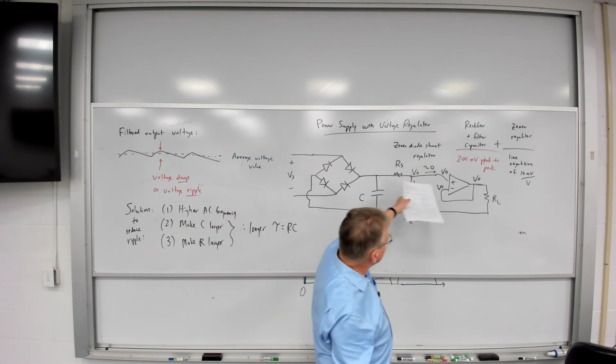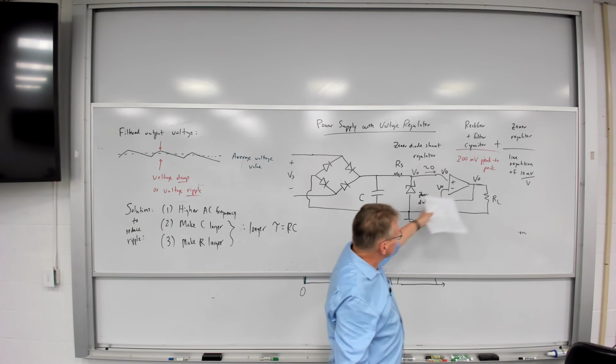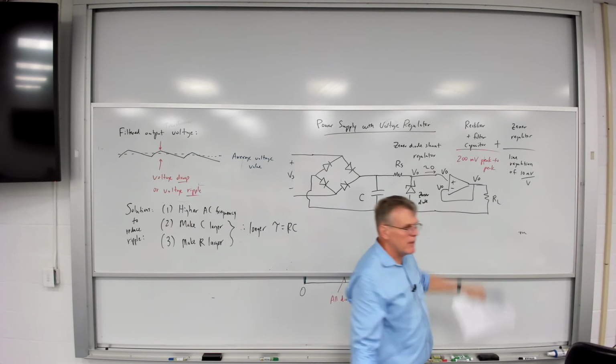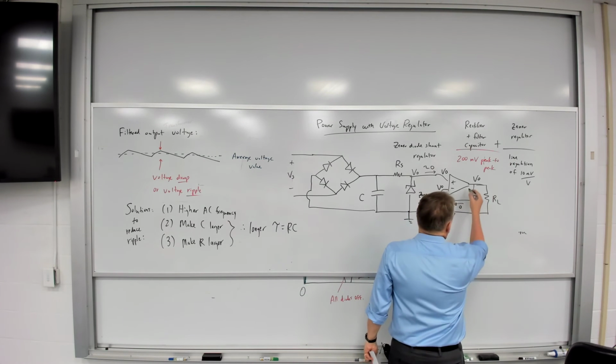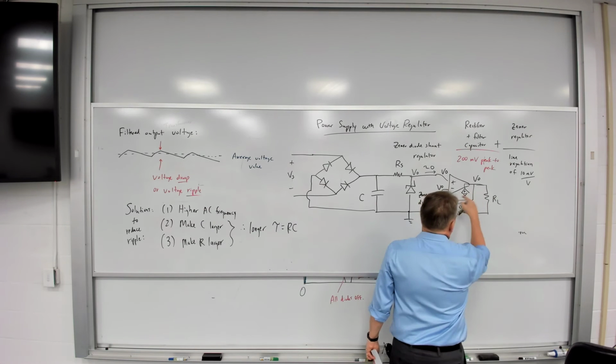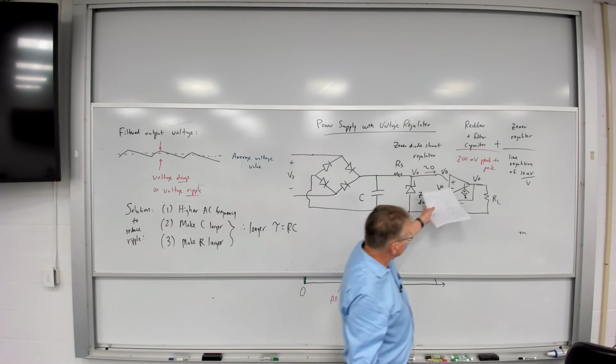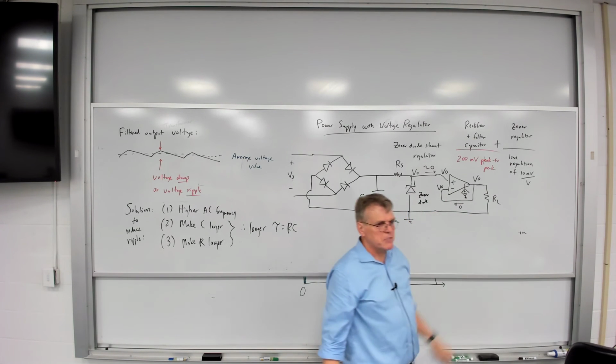So I've got the same voltage here as I do here, except now this voltage is independent of the value of the load resistor, because this current is 0, and remember, the output of an op amp behaves like a dependent voltage source. And so all the current flows out of the op amp, and that supplies our load resistor.